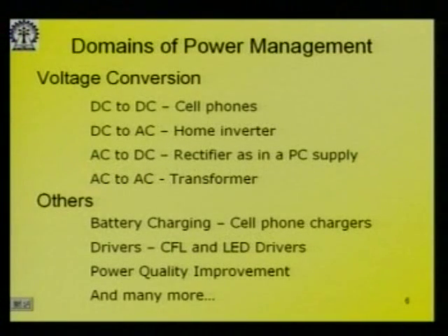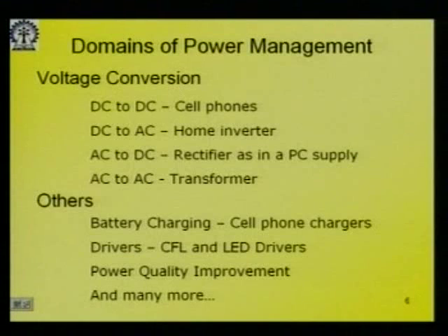And possibly we can have a combination where you are actually capturing solar energy and then directly using it to drive those LEDs. So you don't really bring in AC and other losses. You can save certain energy possibly through that. But you still need some matching. Solar panels will give you some voltage, and then you need to convert it to the voltage that is required for the LEDs. Possibly you have to boost up, because each solar cell will be giving you just less than a volt, right?